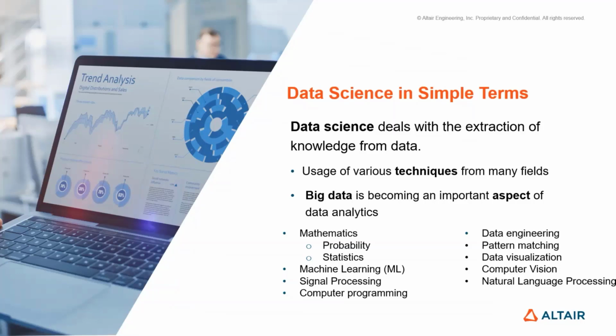So nowadays, everybody wants to put a camera in real time in front of the part coming from the printer and, by looking at the camera pictures, predict the quality of that part, the surface finish of that. You can also put IR cameras which can take a 3D picture and deep dive into the part, to find any pores or cavities inside that are not visible on the surface. Those types of IR camera pictures can also be analyzed using computer vision.